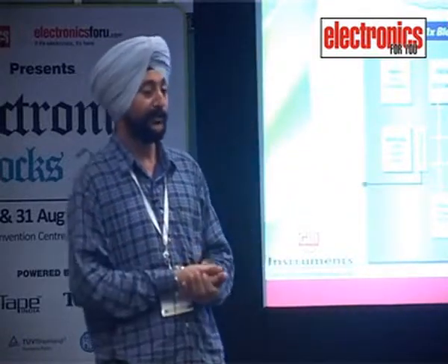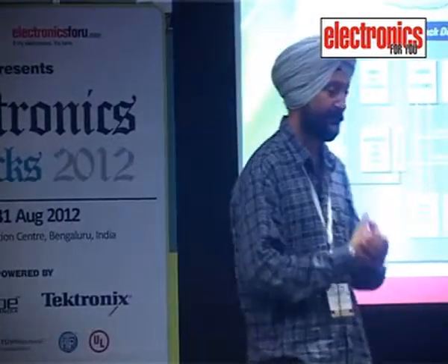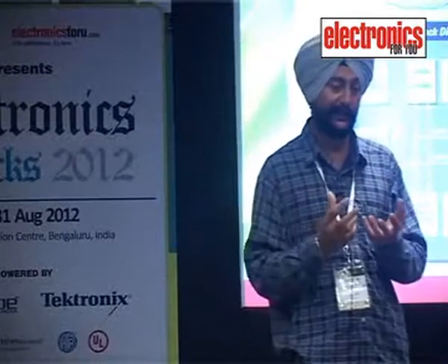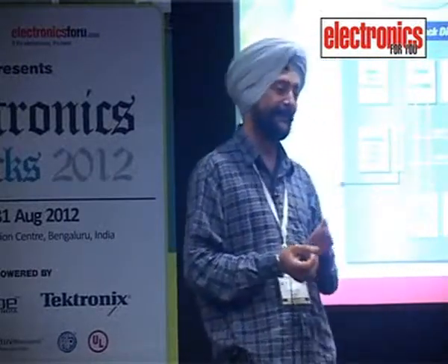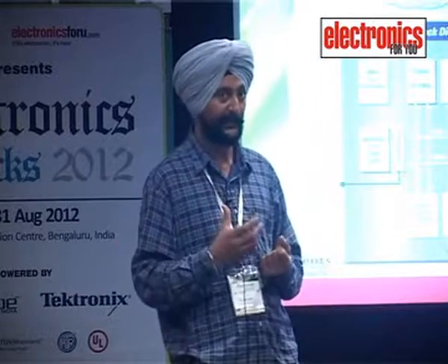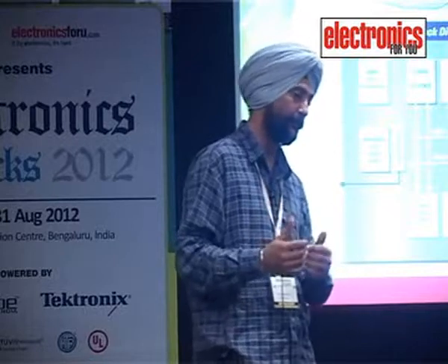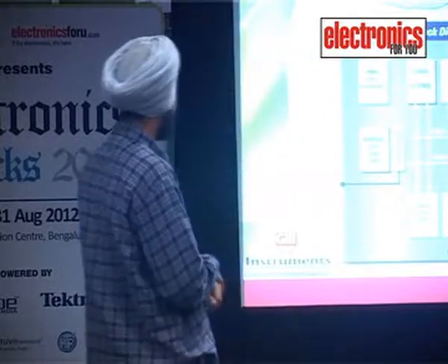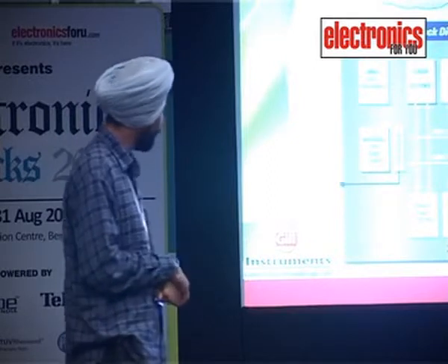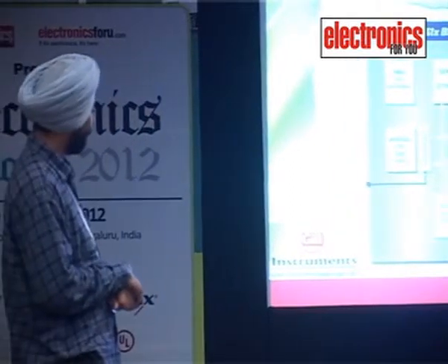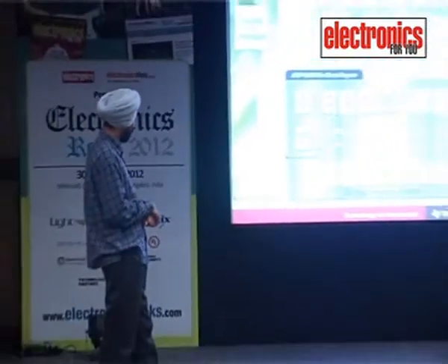Since MSP, as you know, the mixed signal processor, so MSP is not just for one type of signal, so you will be able to get the mixed signals from, let's say you have one group of low speed signals, another group you have high speed signals. So definitely, you need to select two different sampling rates for two groups. So we will be able to do that in this type of ADC. You have a built-in programmable reference voltage. We need not to connect any external reference. We have on-chip reference voltage, programmable.